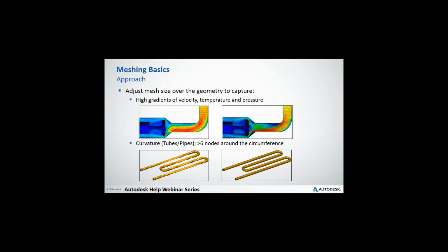Thanks, Marwan. I can also add how the flow passage in this region and the coarse mesh, the high velocity gradients weren't captured, as in the image on the right side of the refined mesh. Here, I've set some examples of geometries where the mesh wasn't well represented.